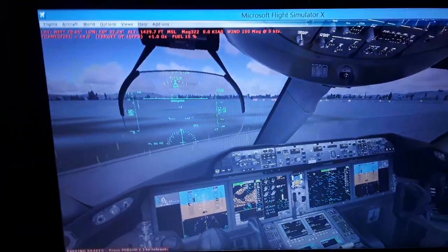and we're going to be aligned with the magnetic heading of 136 degrees of runway 14 at Zurich International Airport, aligned for approach and landing. The STARs are the terminal arrival waypoints and fixes, and altitude and airspeed constraints for the long final approach. The terminal approach and landing of the aircraft is going to be aligned also with the LSZH localizer, the horizontal localizer and the vertical glide slope, which receive the radio frequency transmitted from the threshold antennas of the runways that we have for landing and for takeoff.